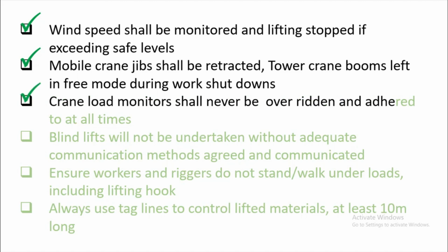Crane load monitor shall never be overridden and adhered to at all times. So make sure that the load monitor is followed at all times when you are lifting a load. If this is exceeding the capacity, stop the operations and bring another crane if you can, or reduce your load weight so that the crane can safely lift the load without any incident or overloading.